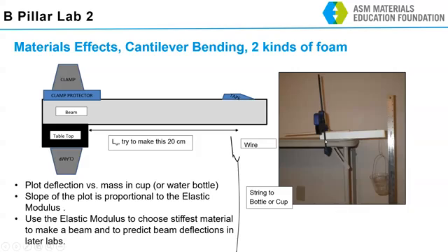So I've got that clamped to my table. I'm using a paint stir stick to keep the clamp from crushing this because this is very low density styrofoam and it's not very strong. I'm using that same weight system again. I've opened up a paper clip and shoved it through my beam. I need something to measure the unsupported length off the end of the table, and I want to try to keep that the same from sample to sample because that's a variable in our equation.